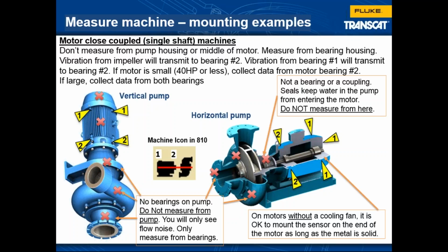In our training manual, we talk about where not to put the sensor. So these are actual slide captures of our training manual. In our training manual, we show you where to take your measurements, where it's good, where it's not so good. The tester walks you through and tells you, okay, on bearing number 2, mount the sensor.